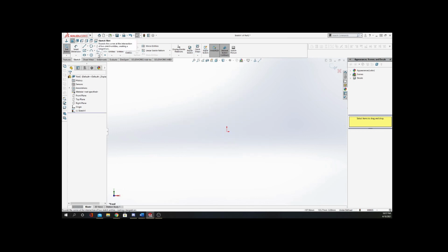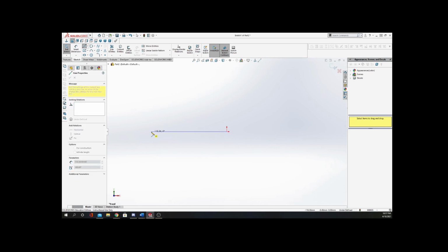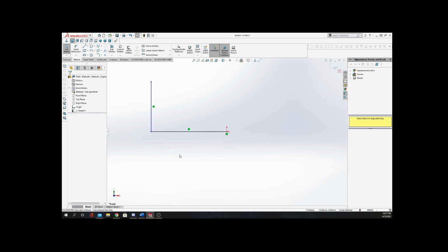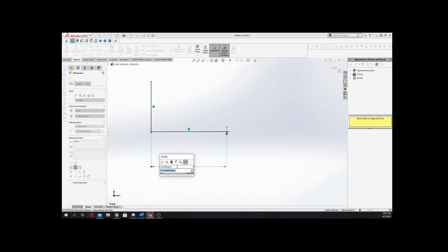And then we have these fillets and chamfers. These are actually kind of handy. You can do these sometimes as a version of your 3D drawing, or you can do them before you turn something into 3D. So you can see here I drew two lines that are perpendicular to each other. I'm not going to bother to give them lengths. Actually, maybe I will, just to make this a little bit more meaningful. Let's say 50 and 50.